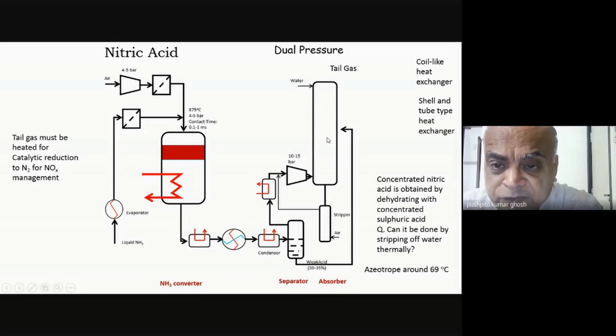When this stuff is again coming out, over here, it is going to come out with about 65% kind of a concentration of nitric acid. And again, the same thing will happen. Again, NO will be formed, right? When HNO3 is being formed. Now, this NO, which is being formed, is again being put back for compression. So twice NO is being obtained, once over here, again over here.